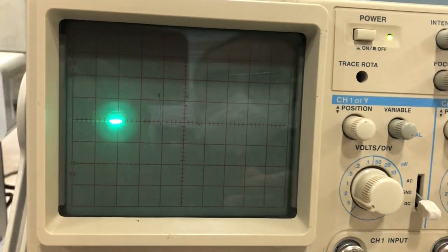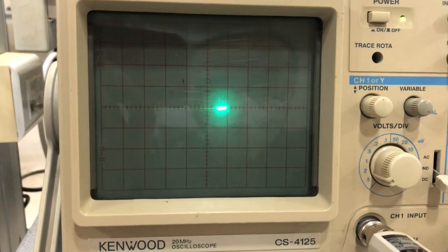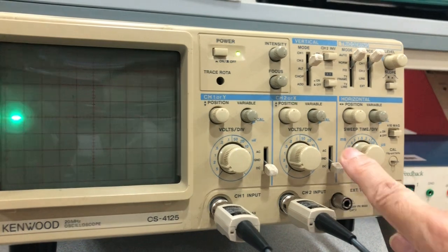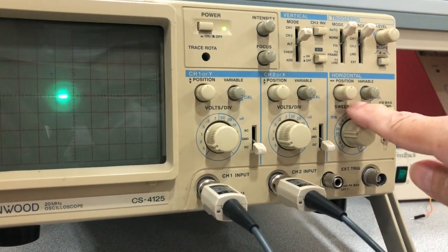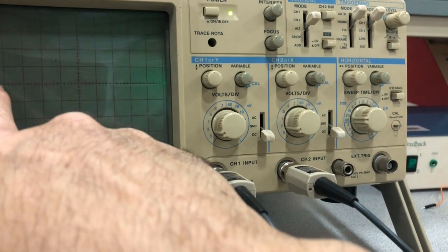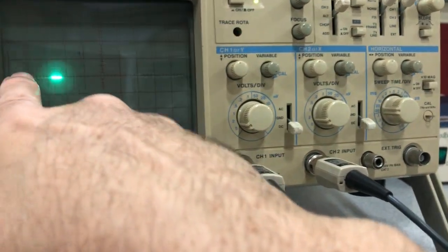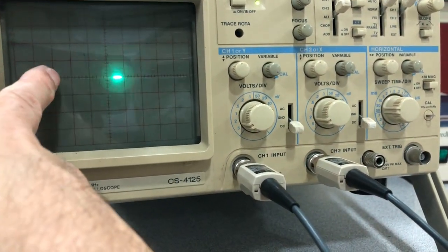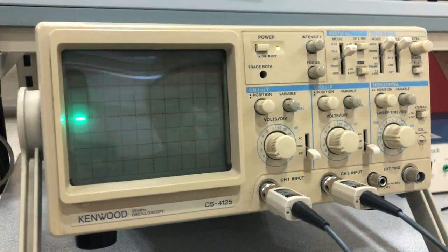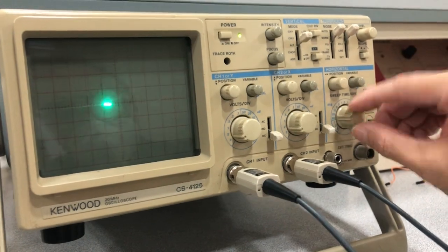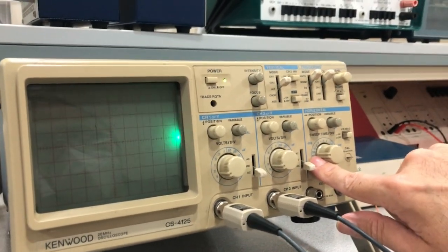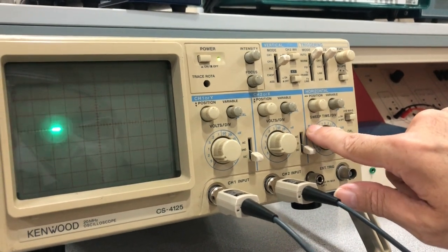If you have a slow frequency, you have to go to a bigger time per division scale. Here it's 50 millisecond per division. It's a sweep time per division. So how long is it taking to cross from one of those vertical lines to the next lines? 50 milliseconds. So the period has to be long and the frequency has to be low to be able to use these relatively speaking large millisecond per division.